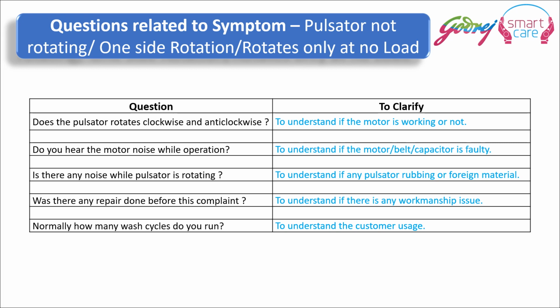Do you hear the motor's noise during operation? It is to understand if the motor, belt or capacitor is faulty. Is there any noise while the pulsator is rotating? To understand if there is any pulsator rubbing or foreign material. Was there any repair done before this complaint? To understand if there are any workmanship issues. Normally, how many wash cycles do you run? It is to understand the customer's usage pattern.